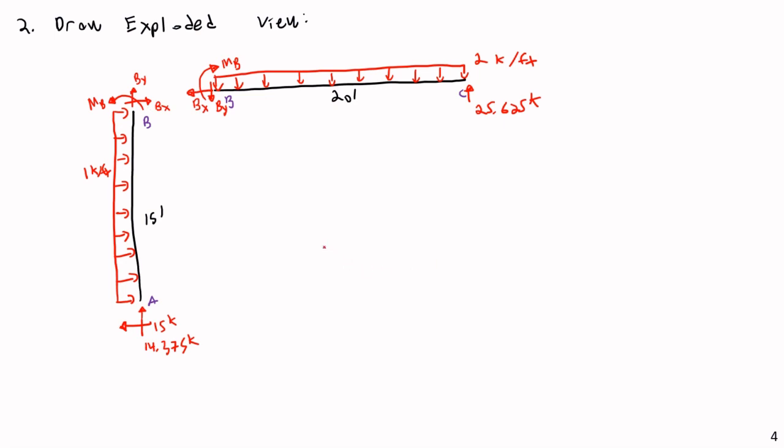So I want to go ahead and get the internal joint reactions. That would be my third step. And maybe I'll just include it on the slides for reference. So 3 would be to get internal joint reactions. And I think I can actually just use the free body diagram of column AB for all of this. You could use the beam as well, but I think I'll just use column AB. Use the free body diagram of column AB.